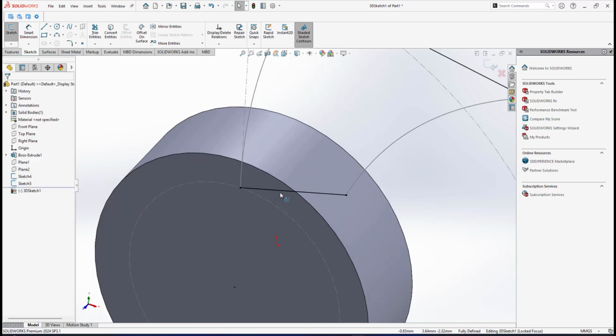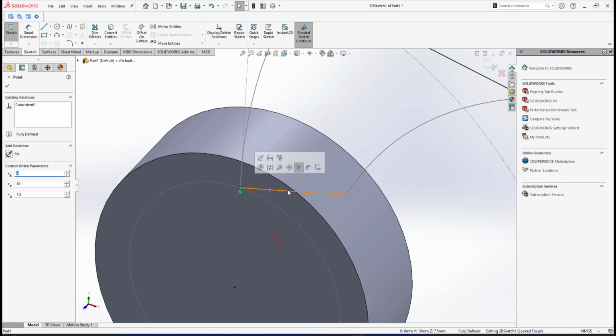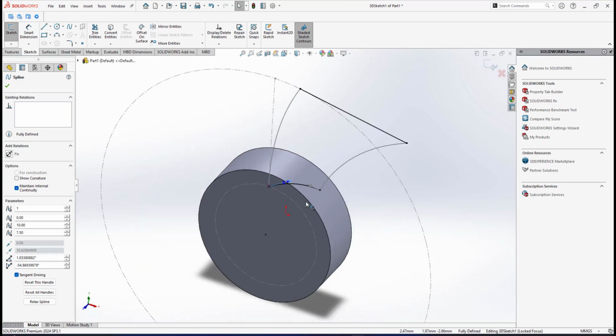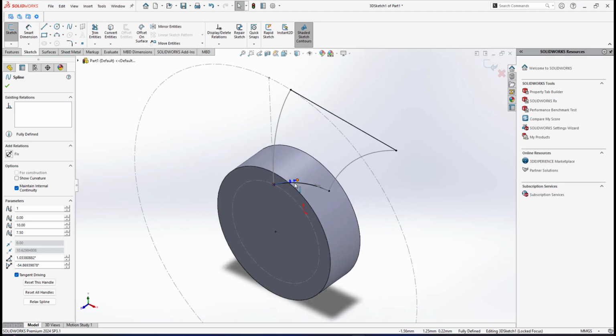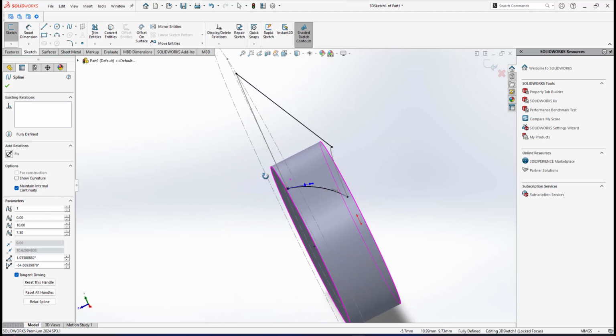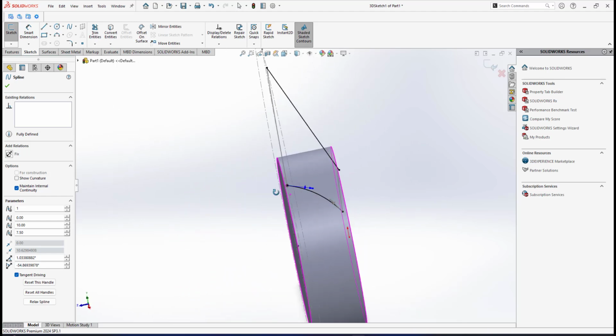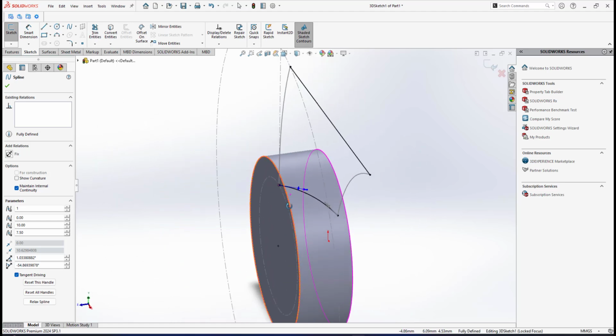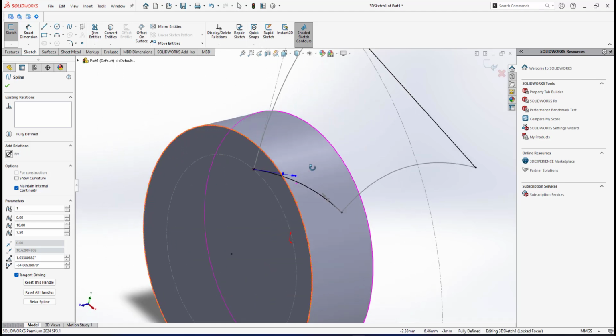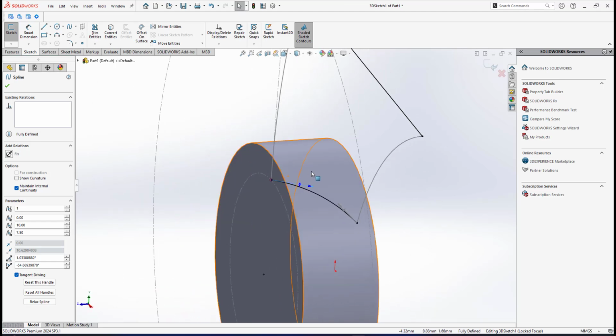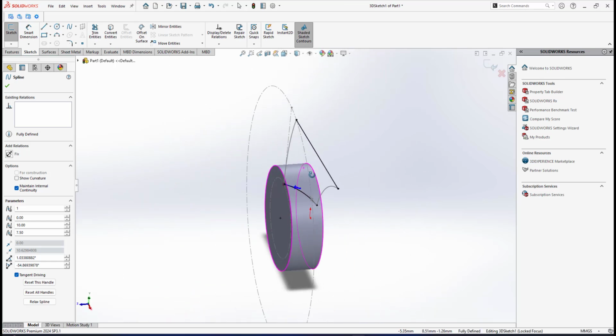All right, at the bottom spline, I can control the handle. Since I have the handle, I can control the curvature. This is a much better way than what you see on YouTube, where they do the fan blade using simply a straight line, then use swept boss, and they have the option of a twist angle. I don't think the result is accurate, because we need this curve for the fan blade. So I can control the curve. That's an advantage of doing the fan blade the way I'm showing you. We have more control over how to shape the fan blade.